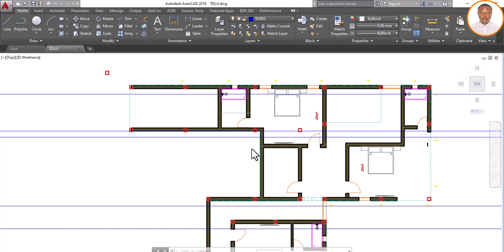And if you look at this also, don't forget our ground floor, we are having a wall on this aspect, isn't it? And if you are now saying that we are shifting a wall inside, then what is going to happen to this slab here? Do you get now? It's even better that we have this column here, and this one shoots out from the cantilever outside, which is still okay.